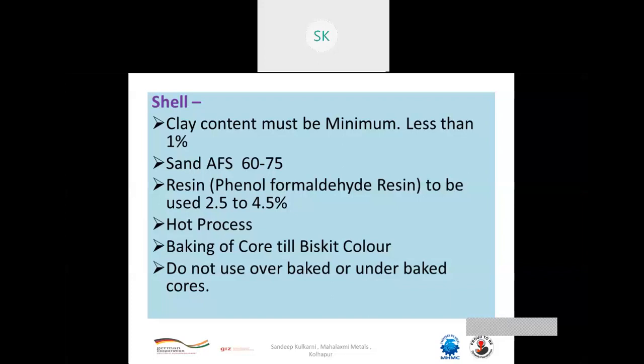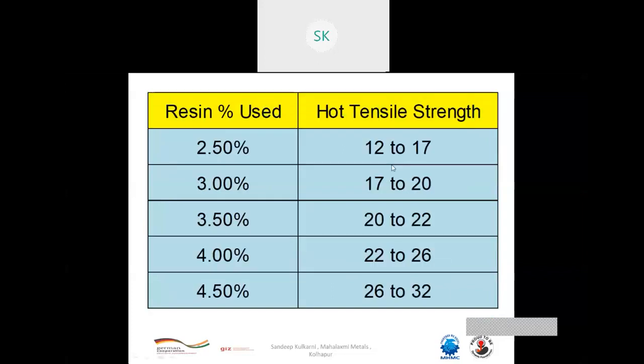Baking of the core till biscuit color is important. This is a very important factor. Do not use overbaked or underbaked cores. I have shown some photographs for your ready reference in future slides.